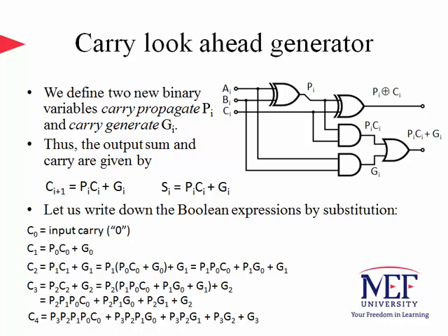This means that we do the same computations more than once, and that adds additional logic to our design. Therefore, at the expense of more hardware and complexity, we gain timing advantage. That is, we do not need to wait for all carries to be computed, and we minimize the gate delay between the input and the output.